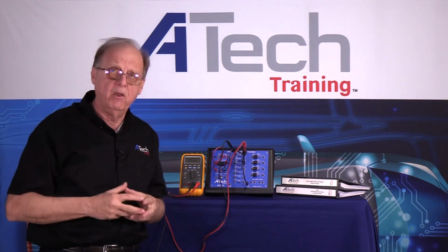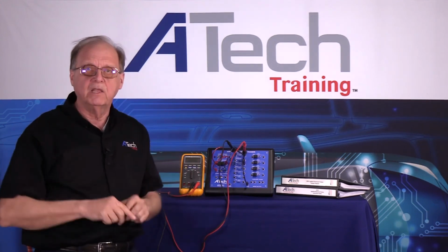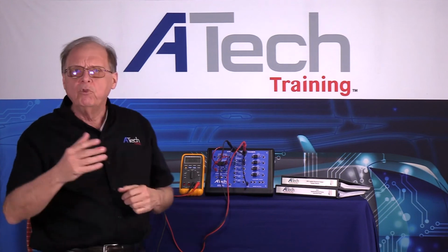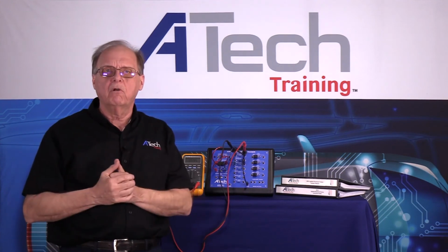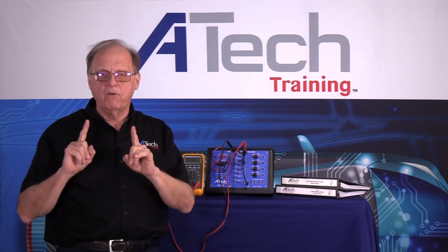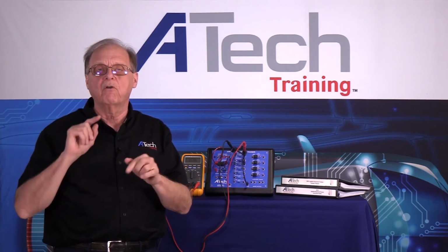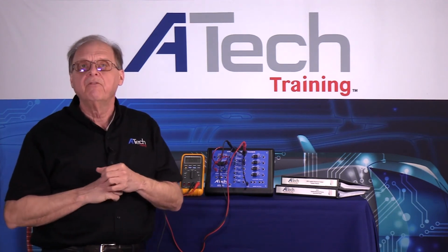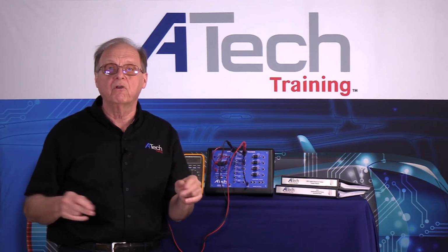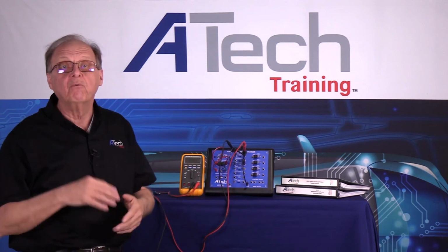If the circuit's in parallel, that means I'm going to divide it in half, basically. When you start teaching CAN networks on cars, you always notice if you go across the circuit and shut it down, if you go across 6 to 14 on the circuit, there should be two 120 ohm resistors in the circuit. If there's two 120 ohm resistors in the circuit, then this will drop down to 60 ohms.